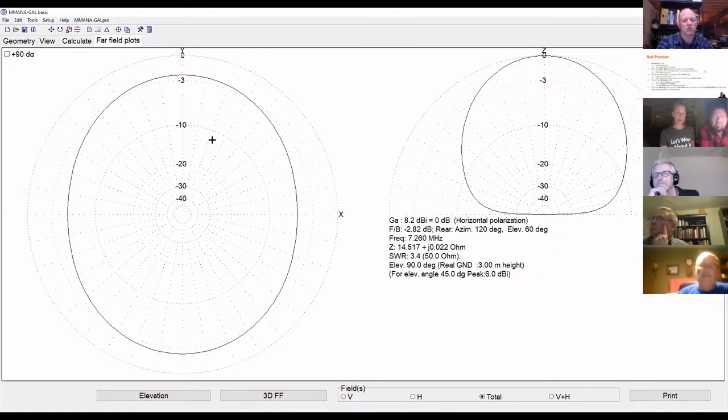And there's a couple things. Number one, this is a mostly omnidirectional antenna, meaning that from an azimuth perspective, it's pointed almost every direction equally, but most of the energy is going straight up, right? We don't see gain from the antenna until we're at like 32 degrees upward angle, right?